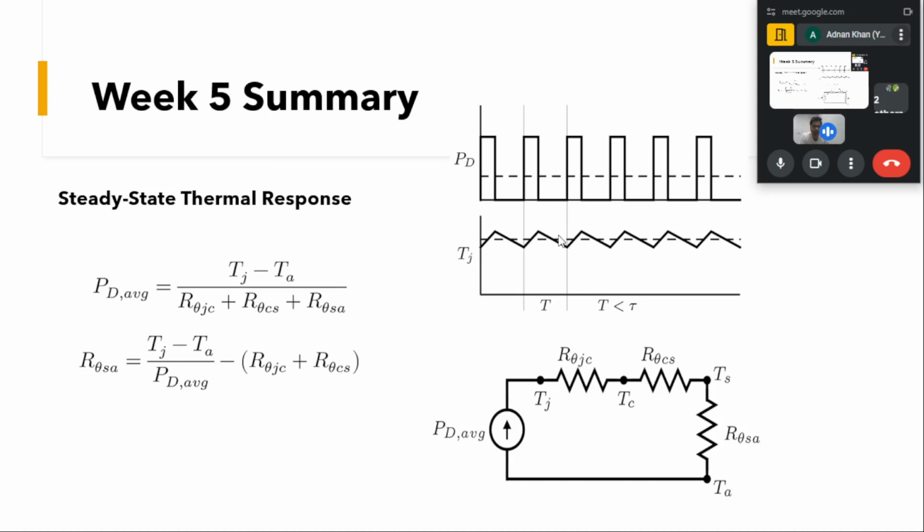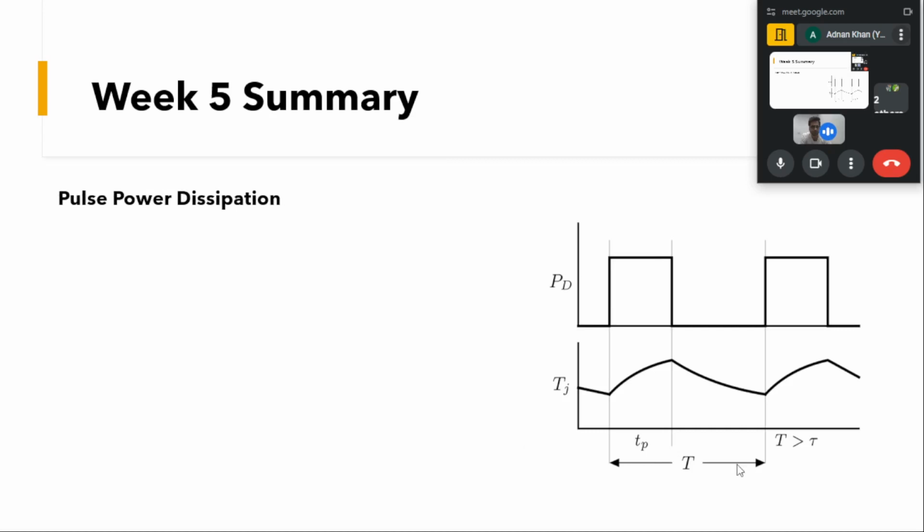This was about the thermal response in the case where the time constant was very high compared to the switching instant. Now for the other case, where the switching time is very high compared to the thermal time constant, what will happen is that for a particular power loss, there will be a large variation in the temperature, and the temperature may rise from one value to another, and the variation between these two temperatures will be very high.